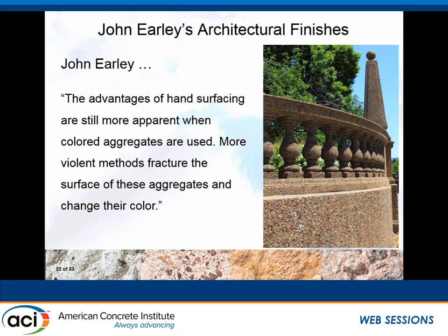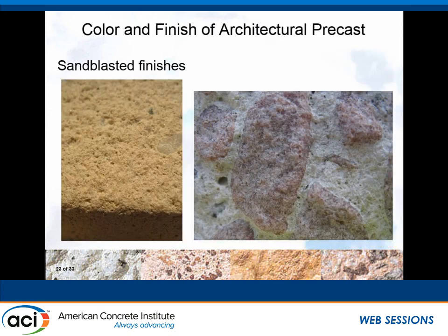One of the things that really caught my eye is that he really didn't like the idea of fracturing the face of the surface of the aggregate, because remember, that was where he got his color. Sandblasting did exist back then, but he's trying to get the color out of the stone. If you do sandblast finishes, you do abrade those surfaces. You really do knock down that bright color that nature has put into place. You fracture the face of that sand and stone.